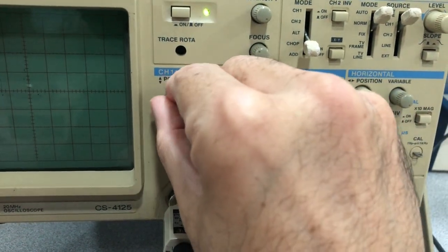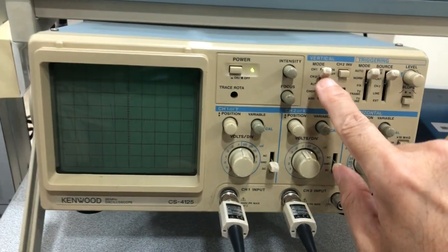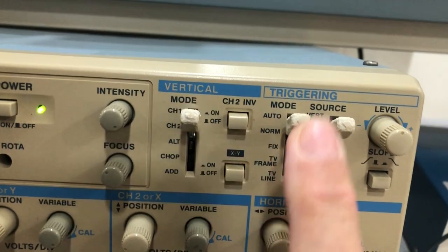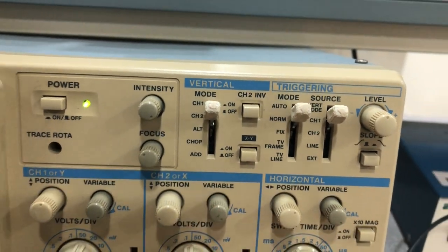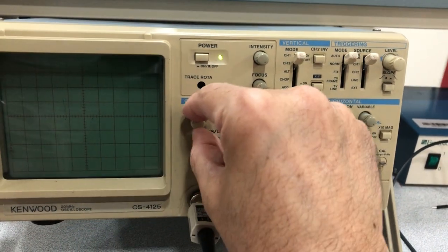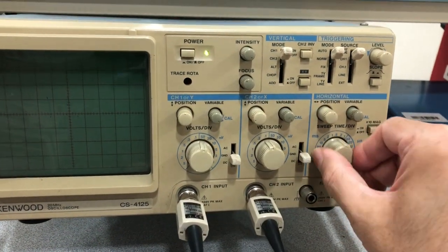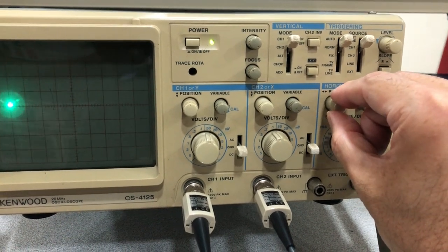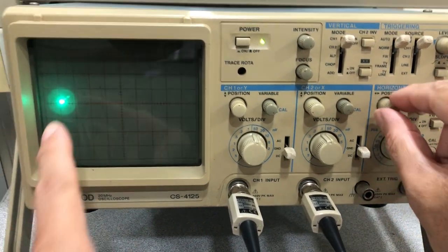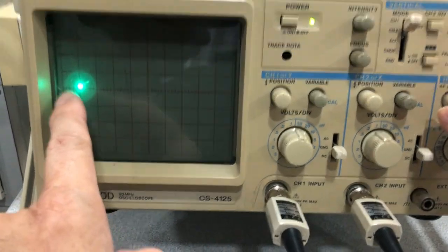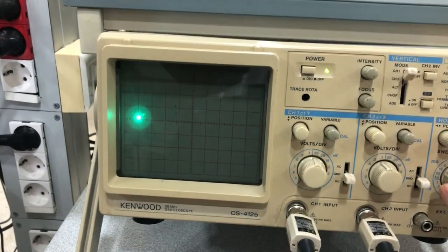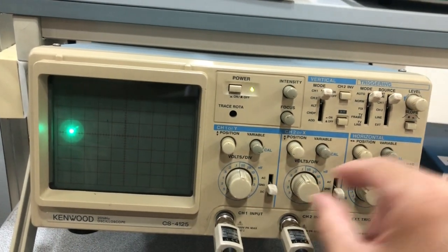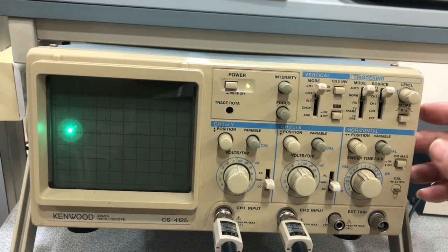I still don't see a signal. So I'm going to go here, mode, vertical, channel 1, trigger on auto. I still don't see any signal. So it's hard sometimes, maybe someone played with the horizontal position. This is the dot that is supposed to be walking to the right now, and it's not, it's frozen. The main thing is we have to see a horizontal line.